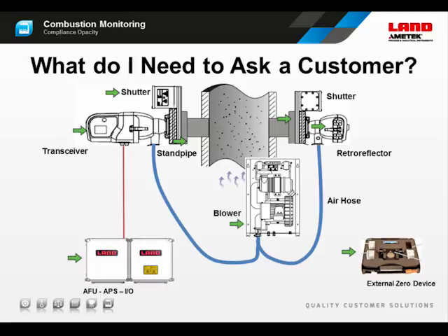And it also allows a simulated zero condition so that the instrument can be audited using standard traceable reference filters. And once a quarter, to comply with EPA rules, users have to install the external zero device and make a series of measurements using traceable calibrated neutral density filters to demonstrate the linearity and the continuing accuracy of the opacity monitor.